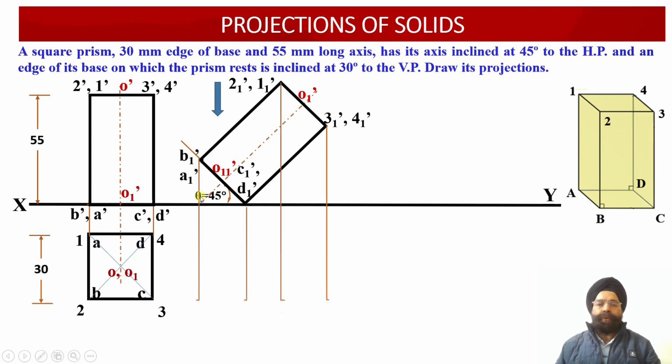we have to draw the projector lines from all of these 10 points in such a way that these vertical projectors need to be extended into the top view projection area, and then we have to draw the horizontal projector lines from the previous plan projection view 10 points over there. So once we draw the horizontal projectors through these 10 points, that is 10 points corresponding to the previous plan projection view, then we will be evaluating the points of intersection of the corresponding points into the plan projection view